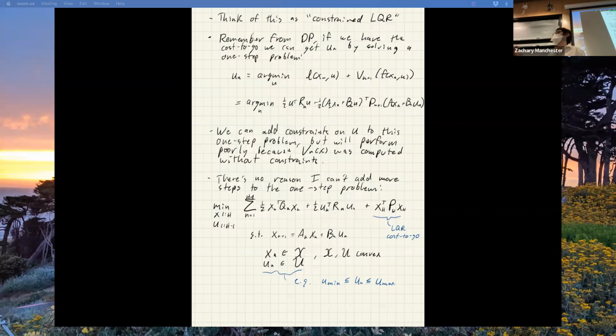I don't want to handicap the system unnecessarily, but the motor can only do so much. You might have other related things for safety reasons, but generally speaking, you want to exploit the full capability. So I don't want to set those artificially smaller than what the actuator's torque capability actually is, usually.